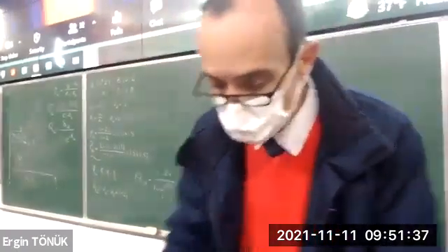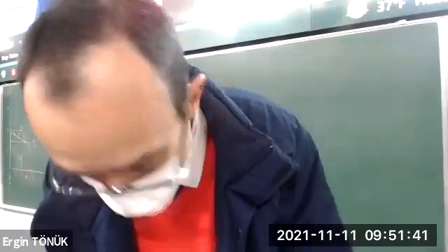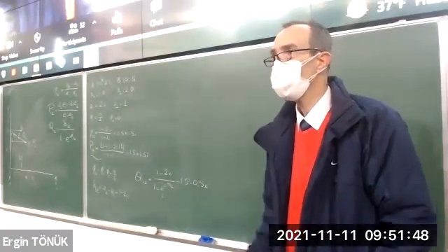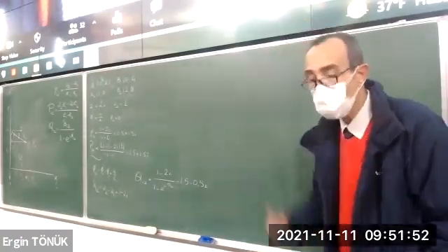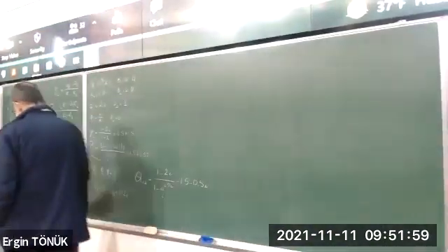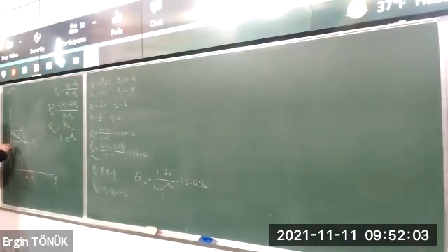So, any questions on this exercise? Is everything clear? So any given motion, we can find the pole. Oh, I was going to find it graphically as well. Let me do it too. So I'll just draw the perpendicular bisector of A1,2. So it's going to be something like this. And then B1, B2. So this is perpendicular. And most probably something like this, B1,2. So it will intersect at the same point. Okay.